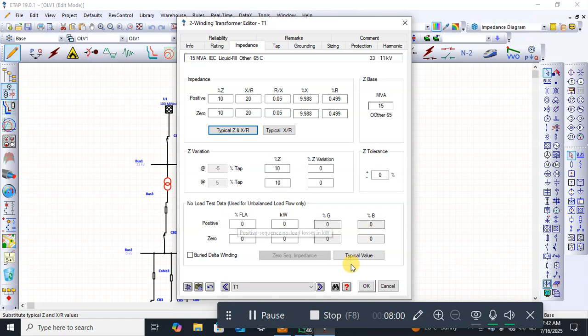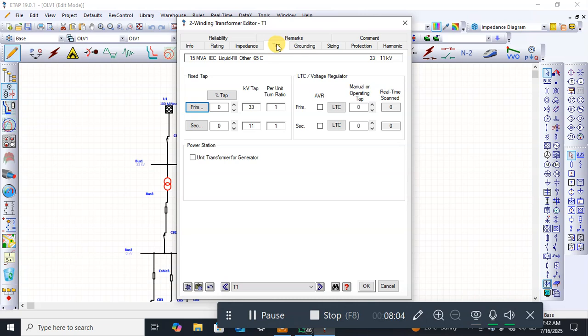Alright, so you click on, okay, so let's try to, if you want to change the type of a power transformer, probably after conducting your load flow, you discover that the voltage at the primary side, at the secondary side of the transformer is low, so you may want to tap it down or up depending on the problem you are experiencing. Maybe you are experiencing low voltage or high voltage. So this is where you tap your power transformer.